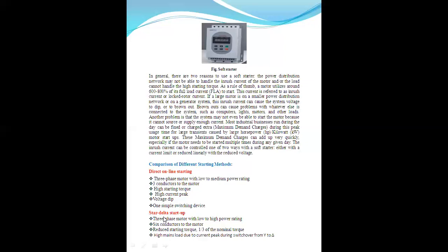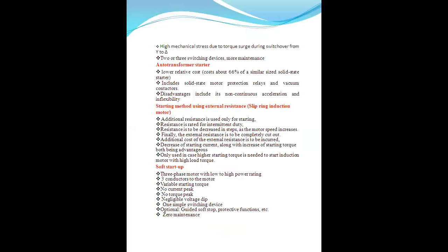For the star-delta starter, it is for three-phase motors with low to high power rating, six conductors to the motor, reduced starting torque, one-third of the nominal torque, high mains load due to current peak during switchover from star to delta, high maintenance, and high mechanical stress due to torque surge during switchover from delta to star. Two or three switching devices are needed, and more maintenance is required.